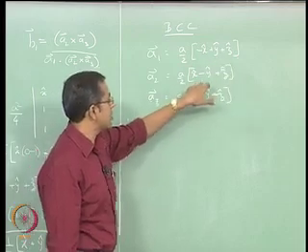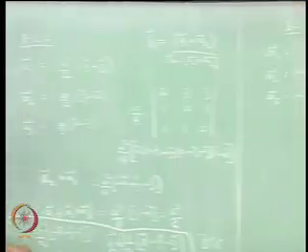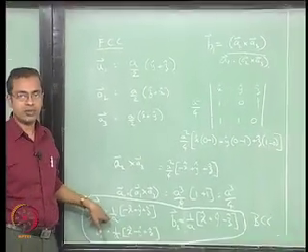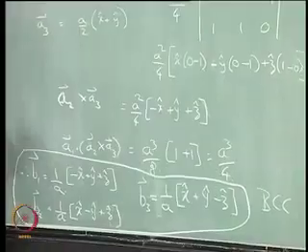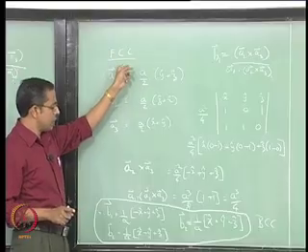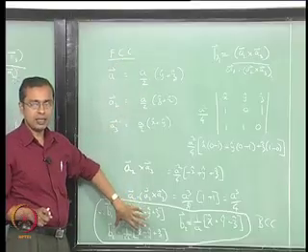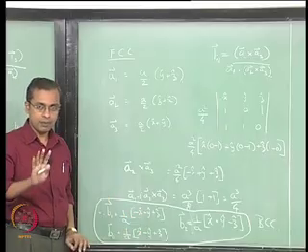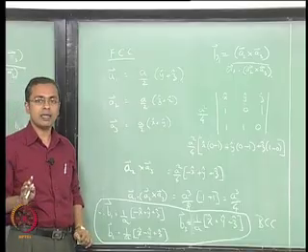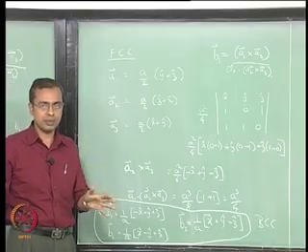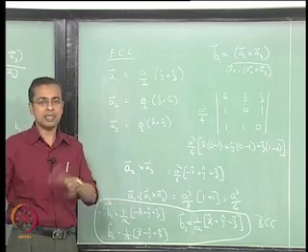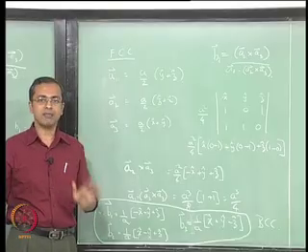Directly you can see that this looks very similar to where we finished off here, exactly the same vectors, only difference is the scaling factor. The scaling factor we need not worry about, but it is the geometry that we are interested in here. The geometry that was face centered cubic as we started out with, when we converted that to a reciprocal lattice notation, it became a body centered cubic. Please keep in mind, as I mentioned right at the beginning, this is only for our convenience, just a notation we use to serve some purpose. The material is still face centered cubic, nothing has happened to the material, it is not that the material suddenly became body centered cubic.